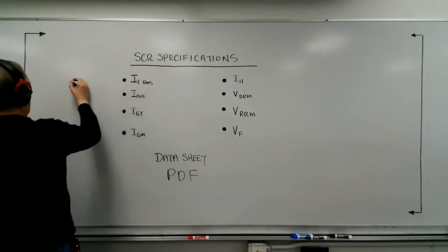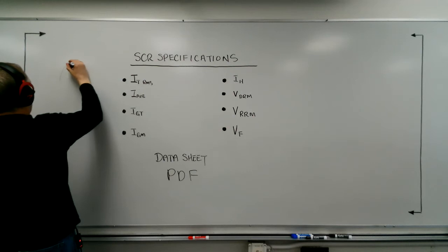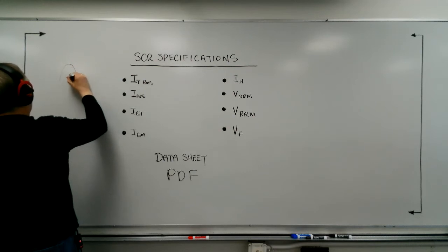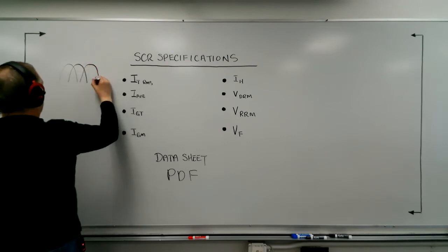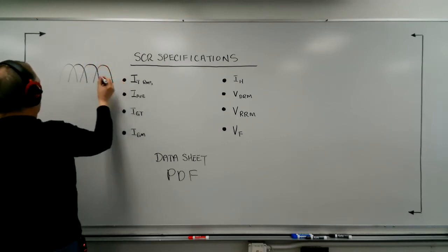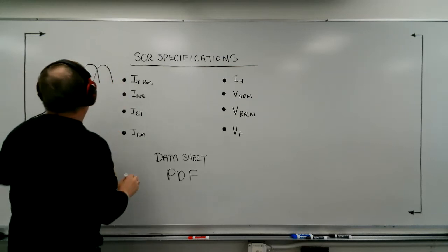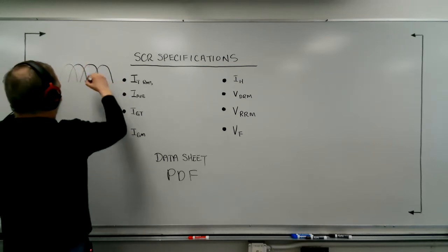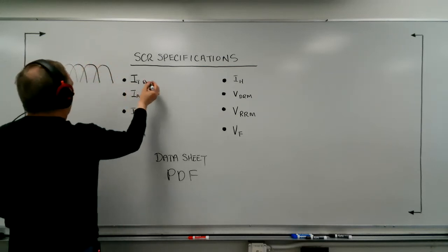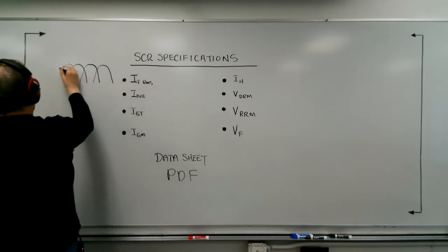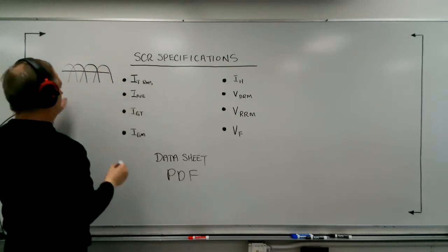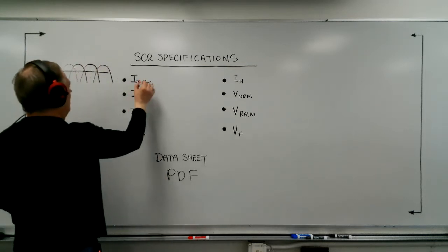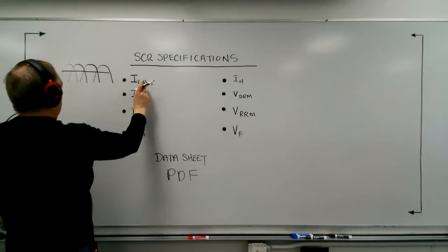You can have an SCR in a circuit that has been rectified, that has waveforms like this appearing between its anode and cathode. Because the voltage will actually be down here somewhere, but you have these peaks being expressed across it, it's going to change the value of current that this can handle.